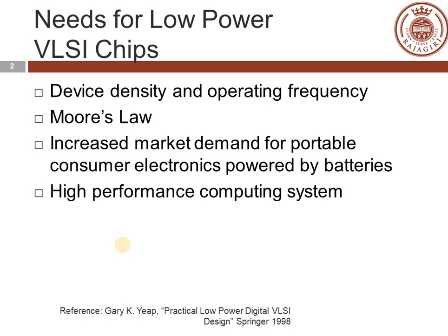A chip that operates at 3.3 volt, consuming 10 watt means that the average current is 3 ampere. The transient current could be several times larger than the average current. This creates a problem in the design of power supply rails and poses big challenges in the analysis of digital noise immunity.